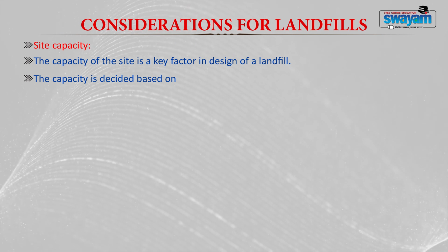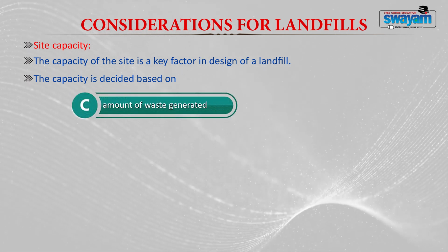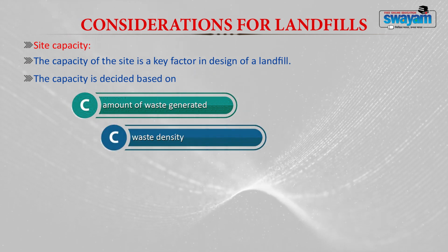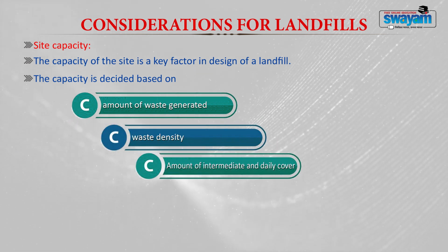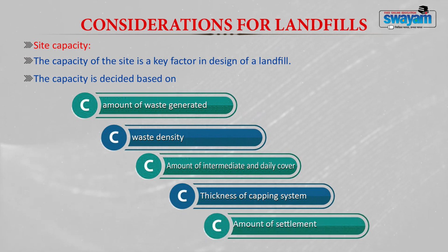The capacity of the landfill is decided based on: 1. The amount of waste generated, 2. Waste density, 3. Amount of intermediate and daily cover, 4. Thickness of the capping system, and 5. The amount of settlement that occurs in the landfill.